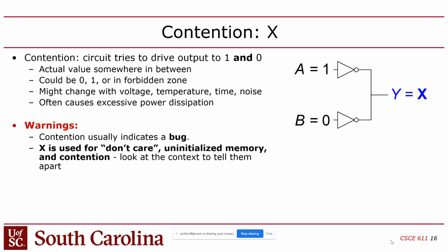So now you might say, why are you bringing this up? Who in the heck would ever do that? Well, it turns out that it's very easy to make this mistake in Verilog, because you don't actually draw wires in Verilog. You just create symbolic names for something that represents a wire or a voltage at some point in the system. And then it's very easy to set that variable at 2 different spots in your code. So this comes up quite a bit.